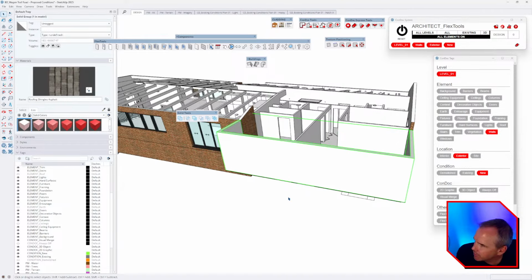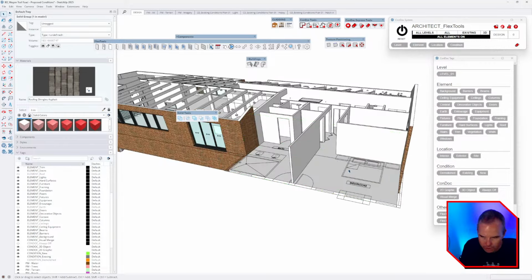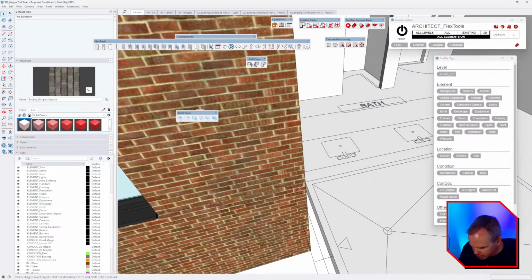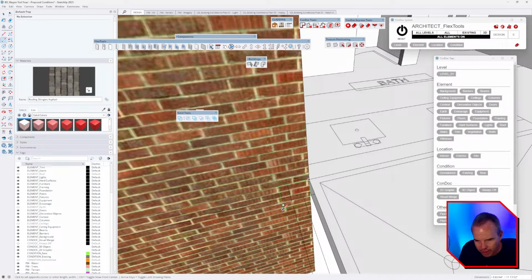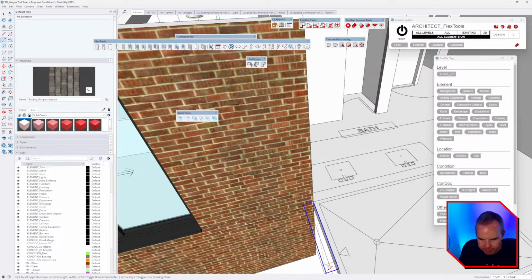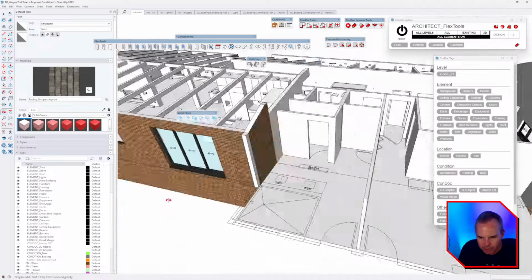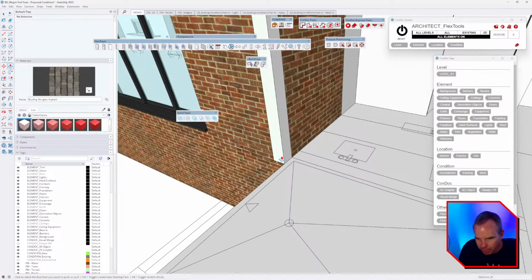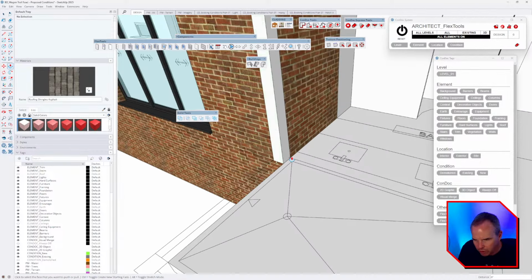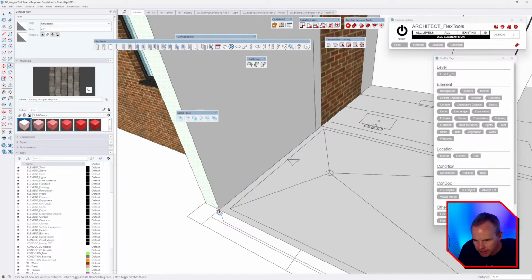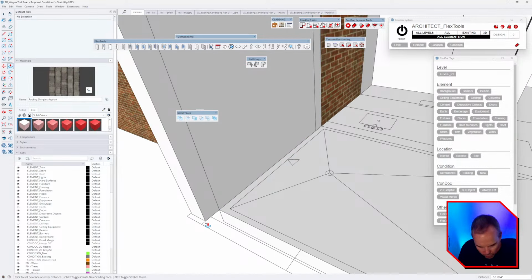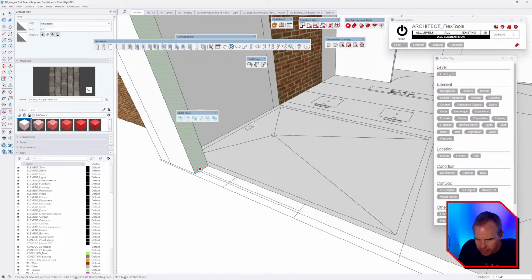So I guess that really begs the question, is it better to draw your walls with that wall tool, or what I'm used to doing is tapping the up arrow key, and I would draw a 6,6, enter, and then I'd pull this up to whatever needs to be, and then pull this out, tap Control, and turn the corner with 6 inches, and then pull it back this way.